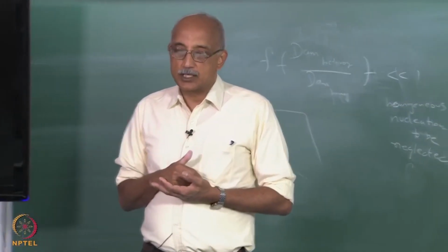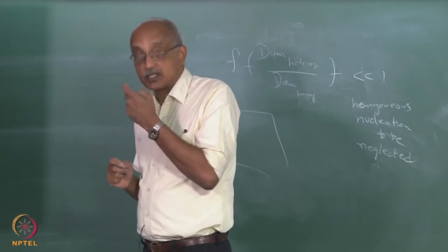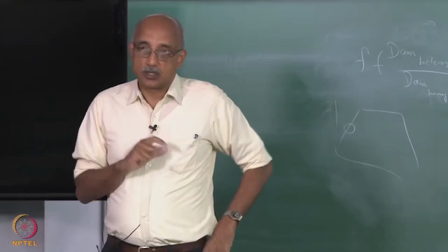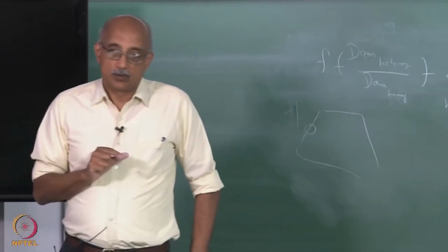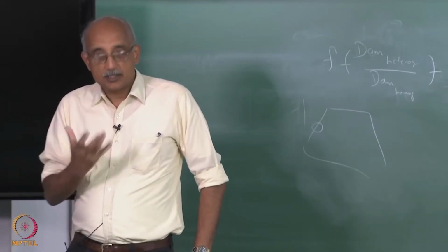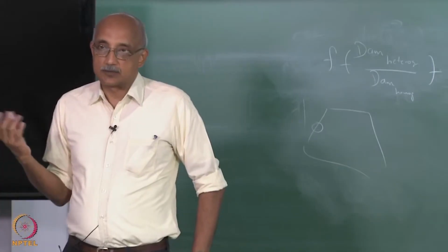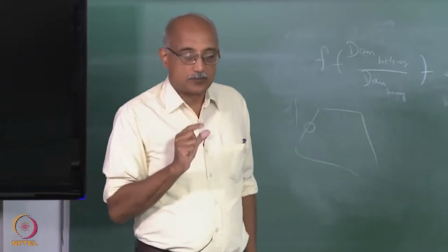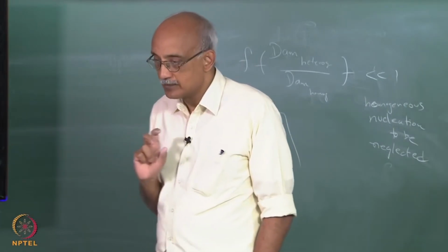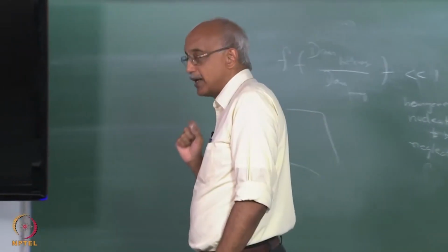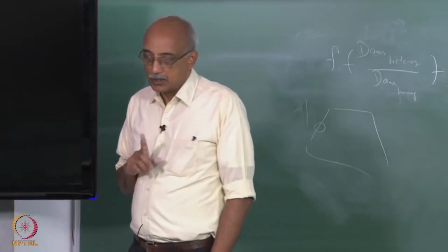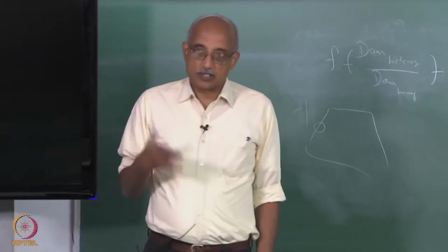And so, the sticking coefficient or the sticking probability or the capture efficiency for a fine aerosol is typically much lower than for vapors. Now, as the size becomes larger and larger, the capture efficiency starts to increase again, but in the middle region, when the agglomerated nuclei size or particle size is of the order of a few microns, the capture efficiency is at its lowest, which means that your material investment has to be larger.